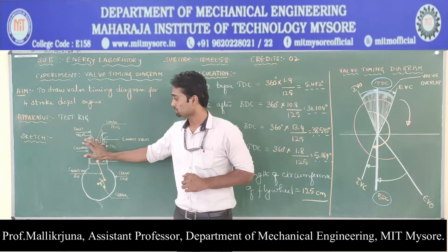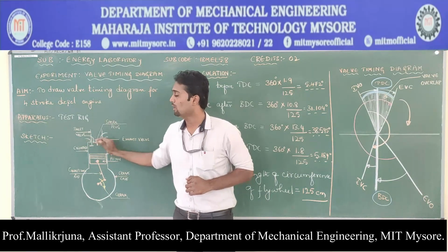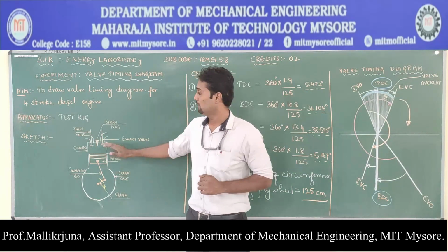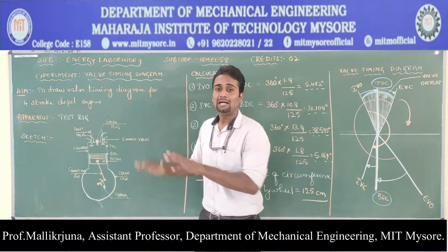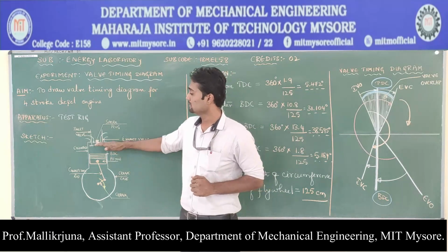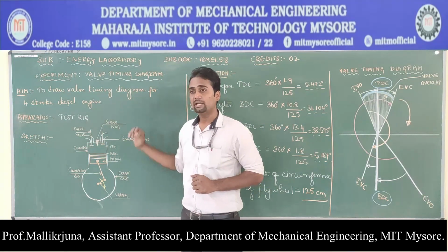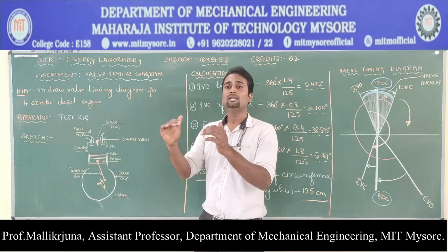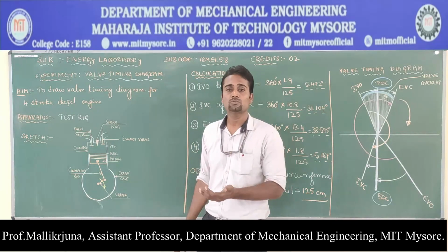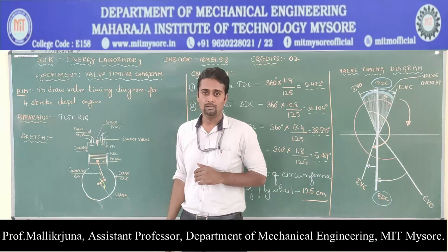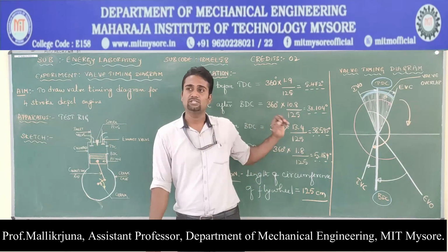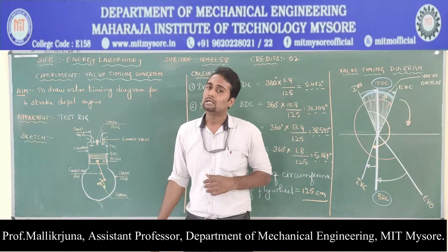So now we need to look onto the valve timing. Valve opening and closing as well as the piston position. Theoretically, what we used to say is the valves will get opened as well as closed at the dead centers. This is what we used to say theoretically, but practically this will not happen. That we will look onto when we reach the valve timing diagram.